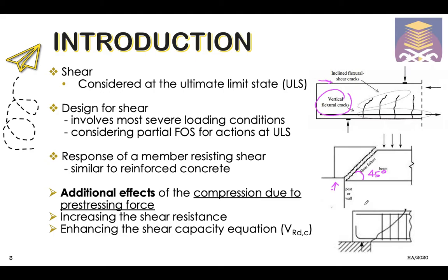So what we are going to do here in the design of shear reinforcement is that we are going to design for this, which are the stirrups. And as for your syllabus, we are going to cover only vertical stirrups, and you can see that these stirrups are arranged in this direction, which is to resist the failure that might be happening within this range.